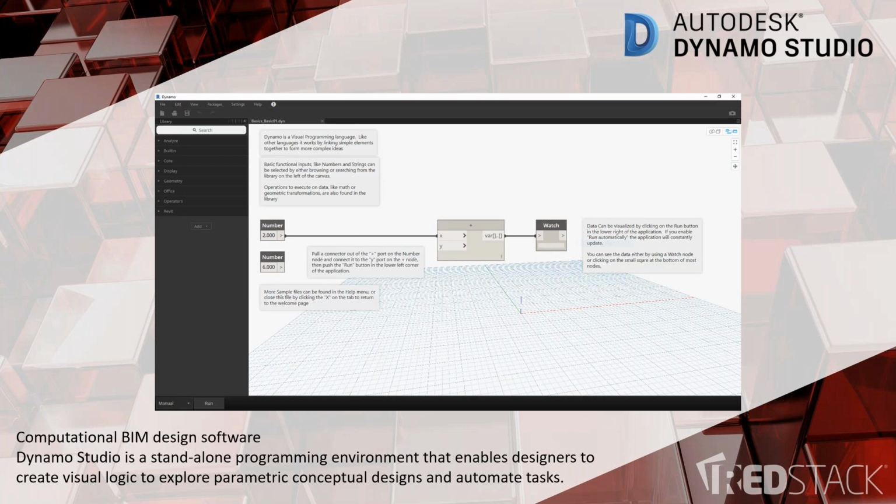But it's really one of those tools where if you're doing repetitive work, instead of having to remodel something in Revit or even Advanced Steel, we can use Dynamo with Advanced Steel as well. We can have one Dynamo script that the users can play and just enter the values as they need to build up whatever it might be in the project.